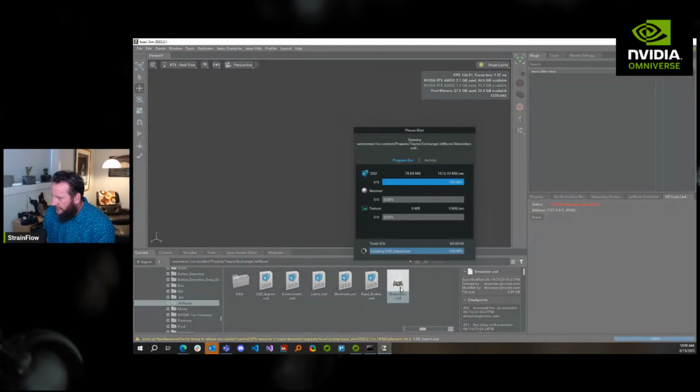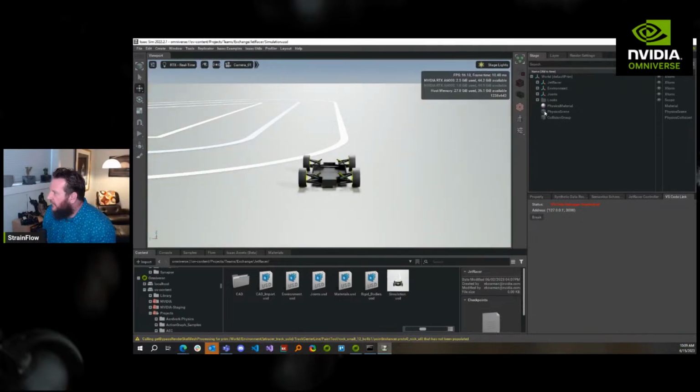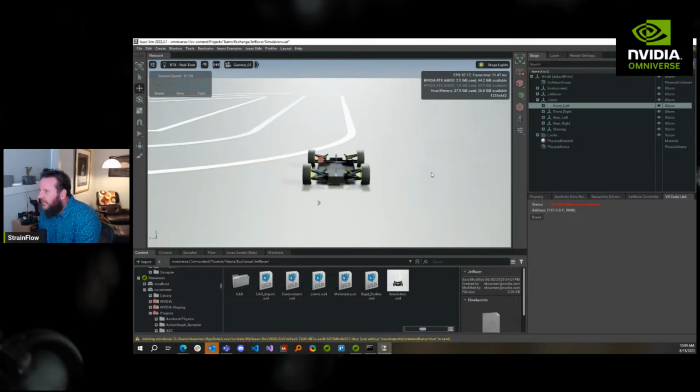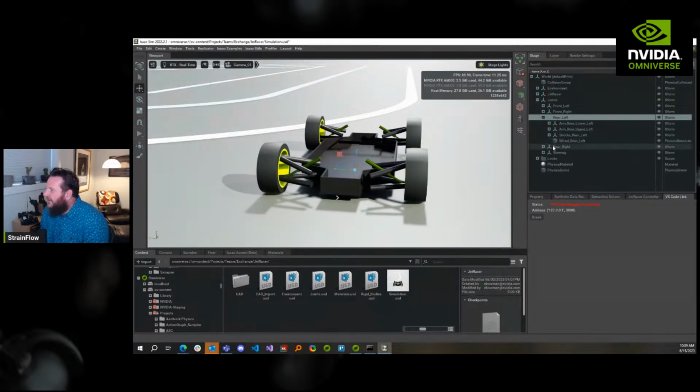There we go. All right. So you saw me rig this front left. I showed it to you, and then the rear left as well. All I did was copy the front. Actually, I had to redo the rear, but I just copied it to the rear. It's a little different because the front has spherical joints on the outside, and the rear has revolutes.